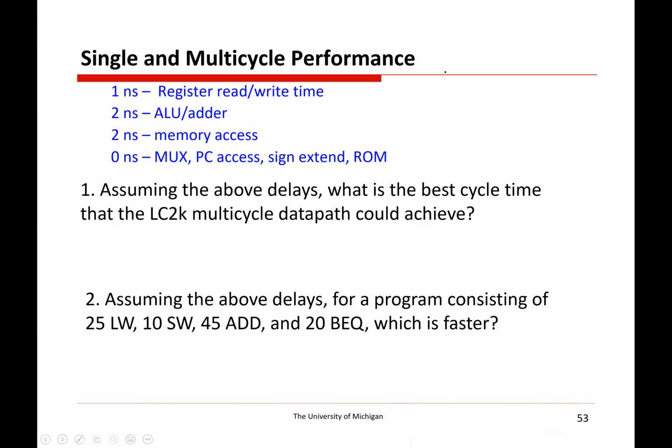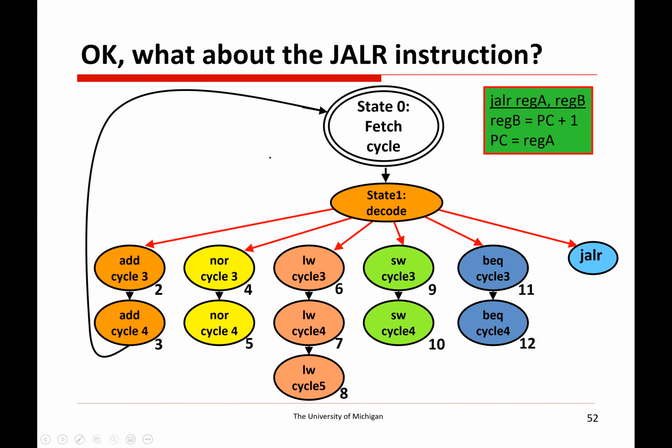So we said that the add instruction took 6 nanoseconds before. This whole process took 6 nanoseconds. The problem was, because we were doing a single cycle architecture, even though we could do an add instruction in 6 nanoseconds, we can only pick one clock cycle. I can't just get 6 nanoseconds into my 8 or 10 nanosecond clock cycle and say, oh, I'm done.